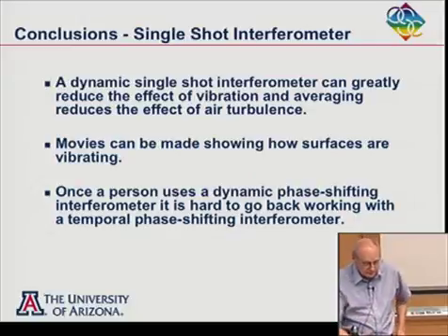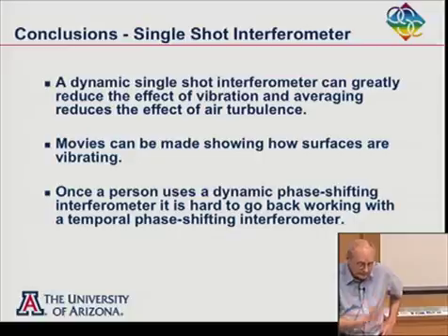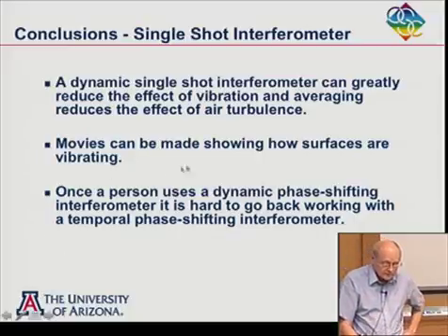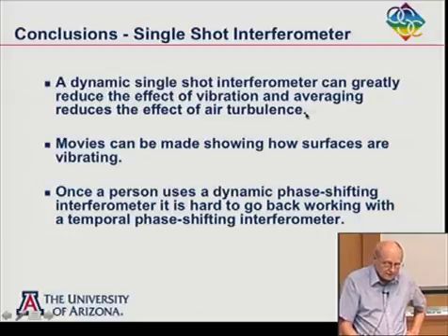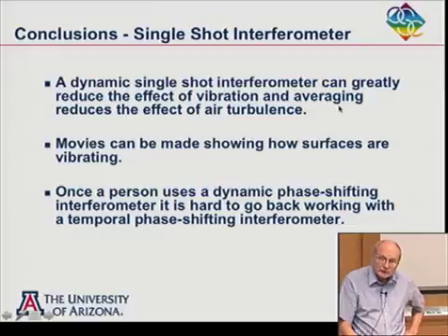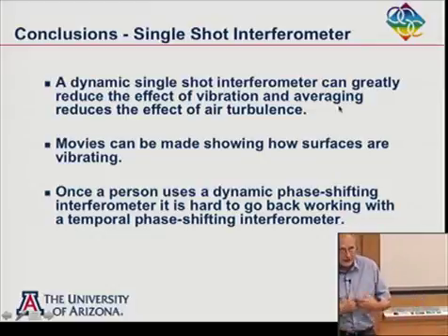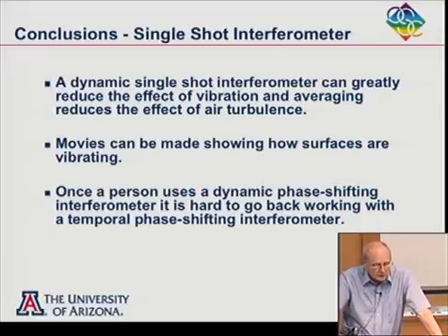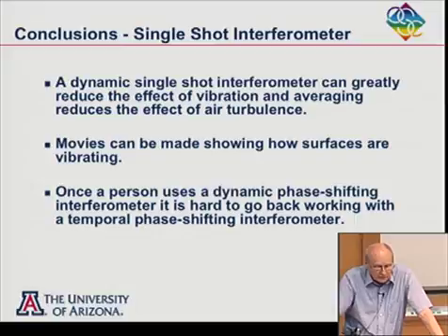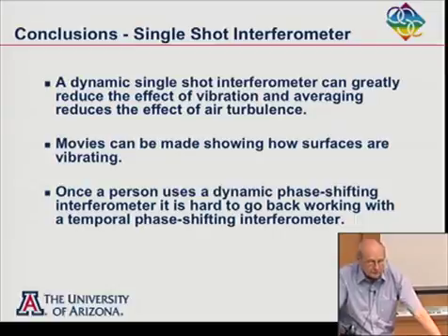My preference is really the last one we talked about, but all these techniques work fairly well. But the conclusion you come to once you play with these dynamic single-shot interferometers, and they're all fairly new, is you really can get around the effects of vibration. You can do testing in environments you never could have dreamed of working in before. Real manufacturing areas, you can get data. You can test large mirrors this way without vibration isolation.